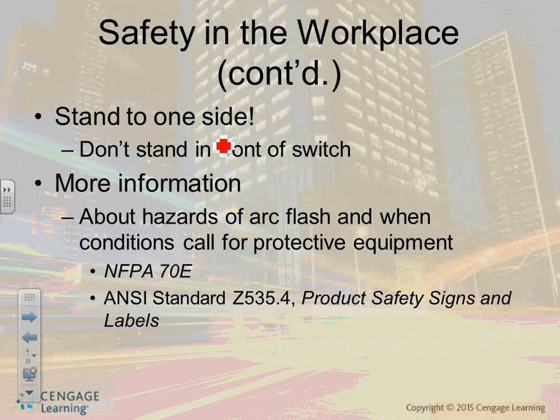If you have an explosion right up in the air, it goes all over. If you have an explosion in the box, that's even worse because it channels the whole energy right into the open area, which is your chest if you're standing right there. You know what I mean? That's why, if the panel is there, they always say stand to the side, because the energy channels right here. Your chances of surviving are higher.